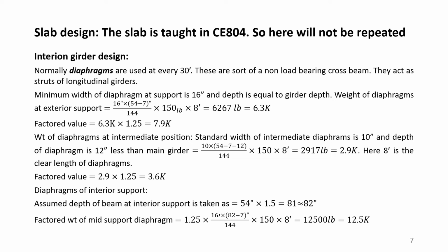At the interior support there will be a cantilever, and that cantilever will support a simply supported span to make the middle gap bigger.